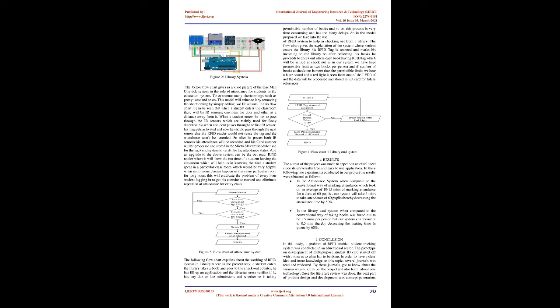Lastly, coming to the output voltage of the Arduino, it has two output voltages. One is the 3.3V output connected to the micro SD card module and the RTC, and the other one is the 5V output connected to the buzzer. Also, two resistors of 220 and 330 ohm value are added to the circuit, which will help in stabilizing the current during any fluctuation. The power source for the Arduino can be of two ways, one being from the USB cable using an electronic device, or the other being a 5V adapter capable of producing 500 mA, used to run the microcontroller and the electronic equipment connected to it.